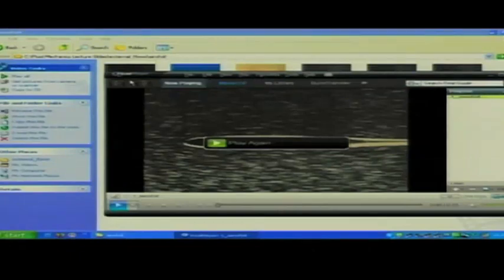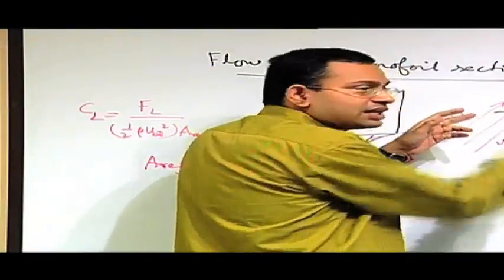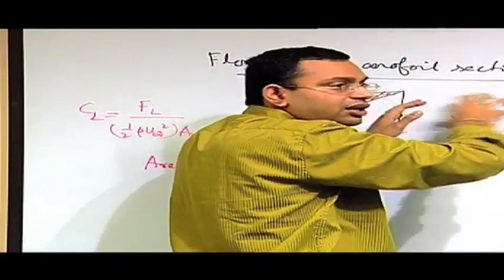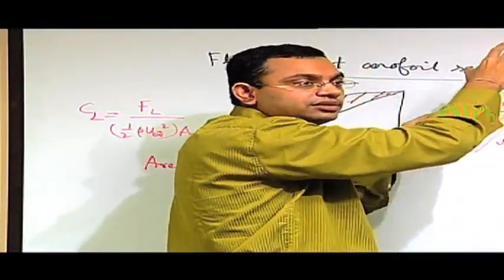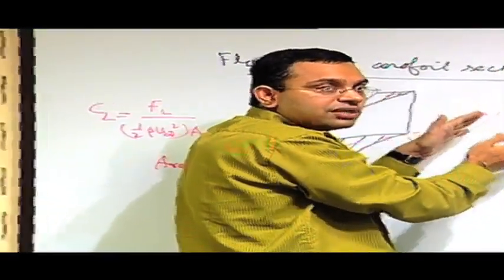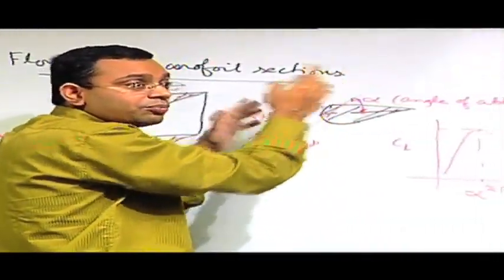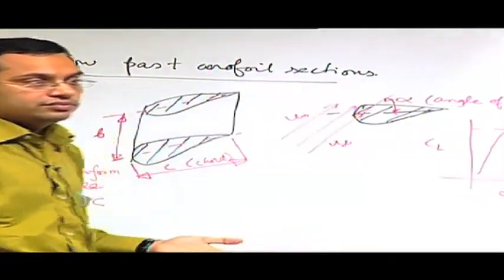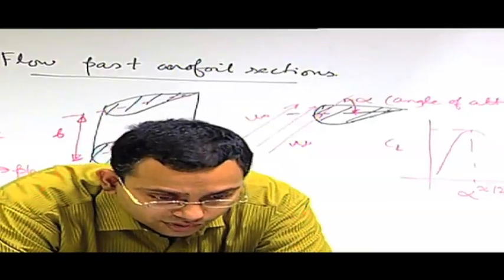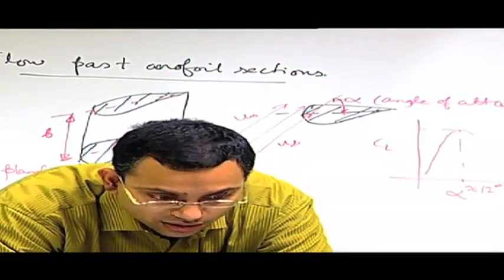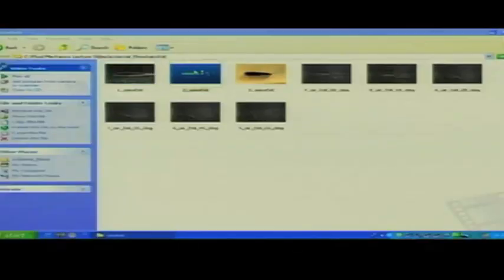That is quite clear. Just think very physically: if there was no separation and the flow is coming from the bottom, it would lift it very significantly. If it is horizontal and inclined with it, how can it lift it? As you increase the inclination, you have a chance of lifting it more and more, but if you have boundary layer separation altogether, then that effect is lost. So let us look into the different cases of aerofoil flow.